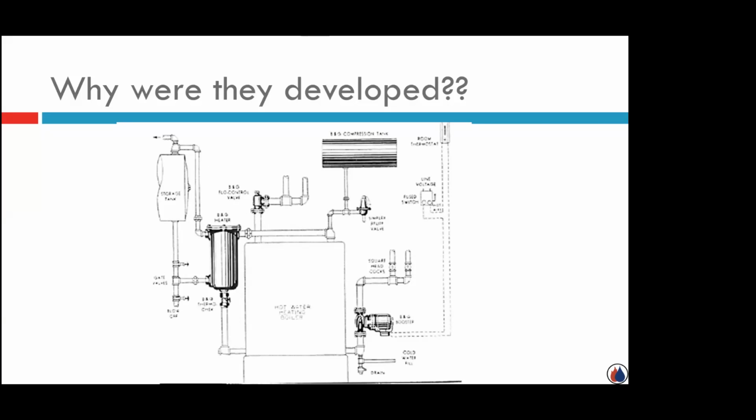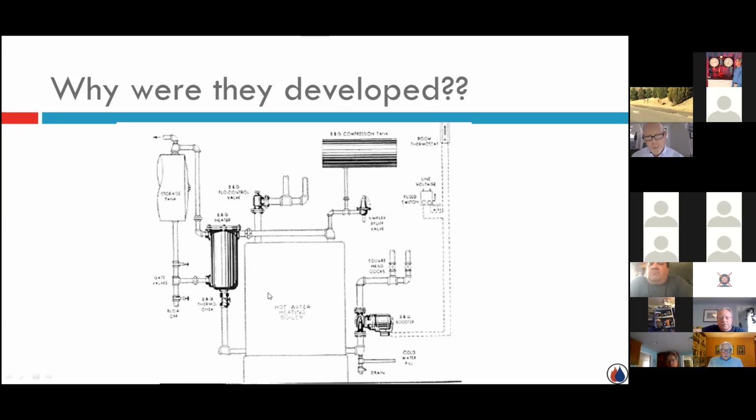But what they also started combining with the heating, using this boiler for heat for the house, they would have domestic hot water located off the boiler. So the boiler would stay hot all the time. Well, they quickly realized that if they didn't have some type of weighted check here to prevent the water from circulating, even in the summertime, I get this hot water, which I need the boiler to be hot to provide the domestic hot water. Heat would migrate, maybe not as fast as if it was gravity hot water because the piping might be smaller, but I would still have heat migrate.